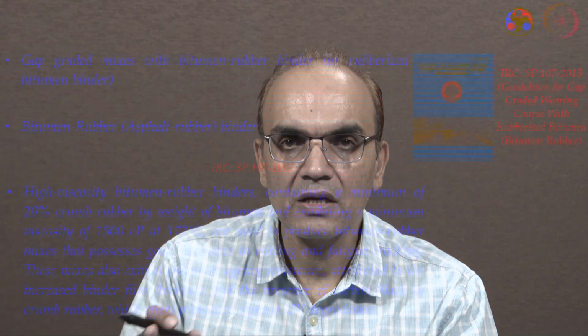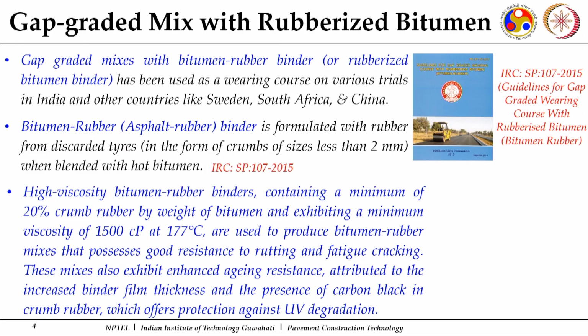So the gap graded mix, especially the one given by IRC SP 107, which is on guidelines for gap graded wearing course mix with rubberized bitumen or bitumen rubber. This particular mix has had good trials in India, along with many other countries, Sweden, South Africa and China, and has been proven to be a mix with good rutting and fatigue resistance.